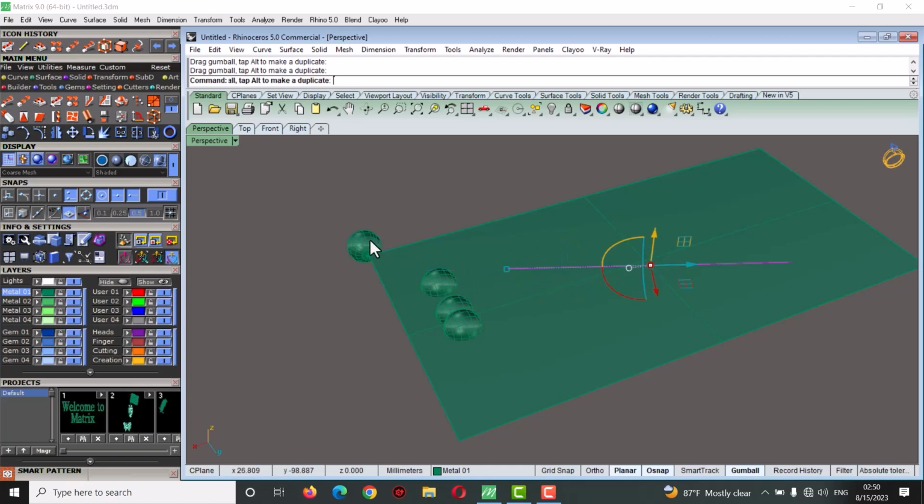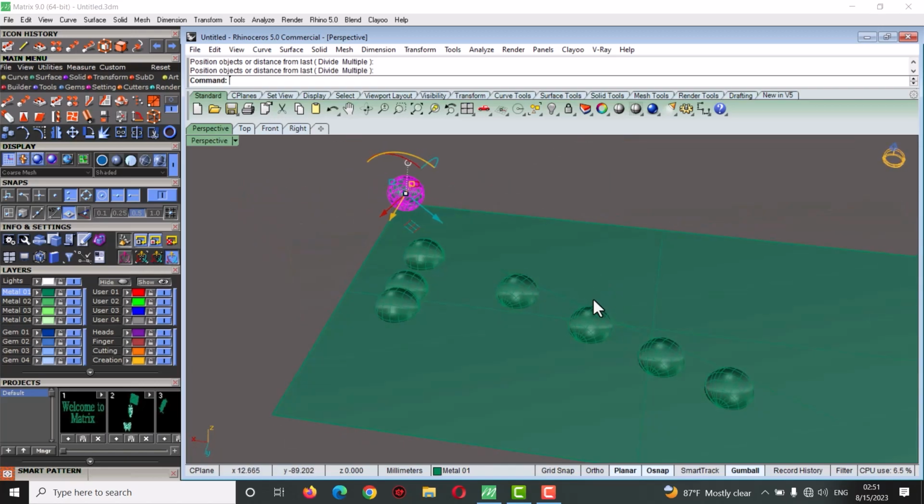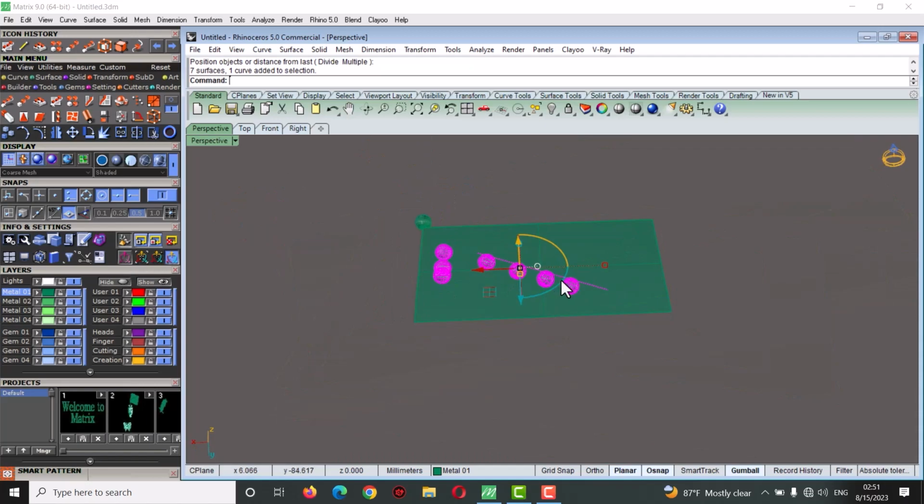Or this one. Select the object, select the array curve on surface, base point here, select the curve here, select the surface here. With this, you can copy your object on a curve of this surface. It's not very useful, but it's a good icon.